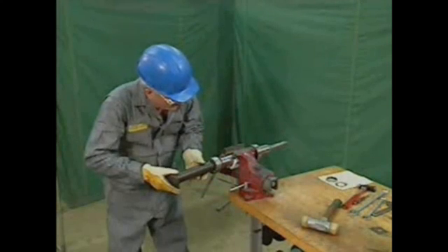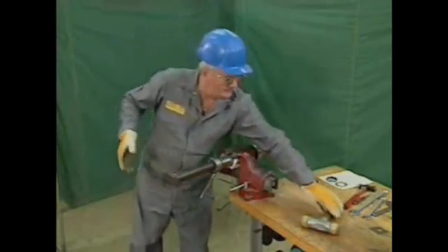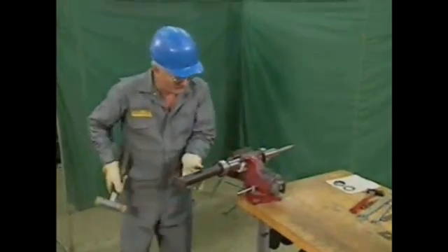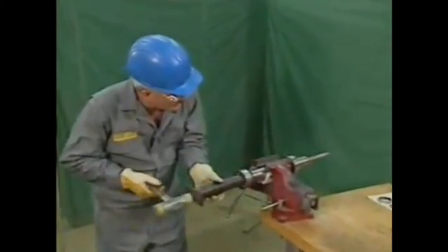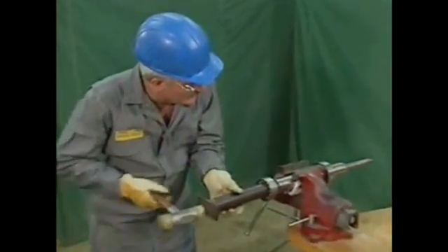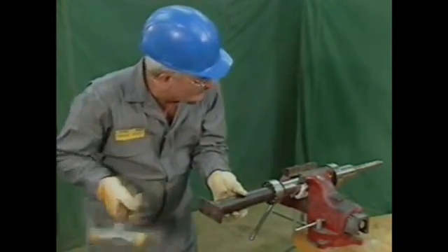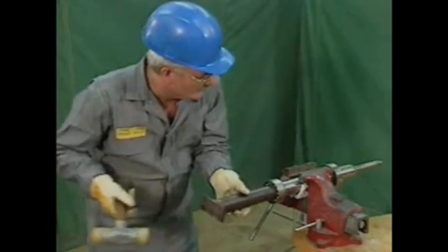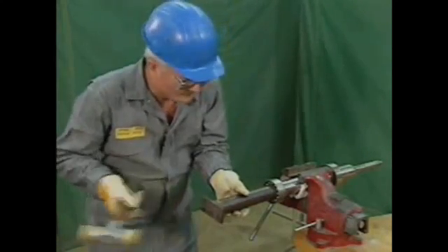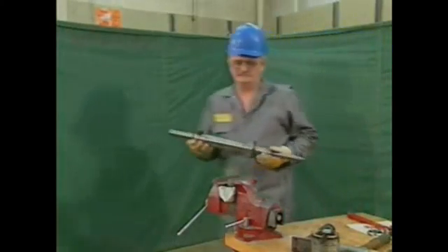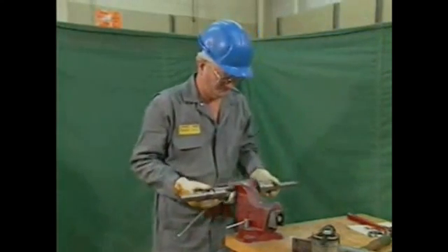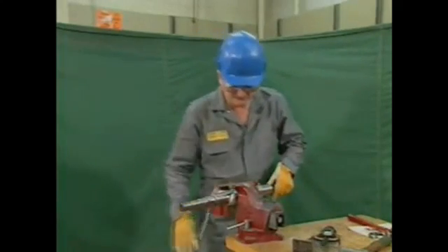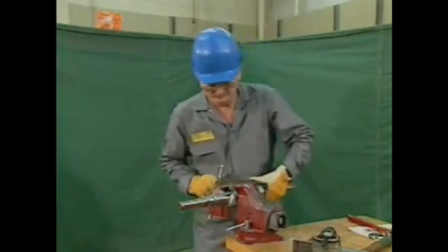When a tubular drift is used, the shaft stays stationary and the bearing is forced down the shaft. This method is generally used when the shaft can be removed from the machine and placed in a vise. If the shaft is left in the machine, its other bearings may become brinelled. The tubular drift method is both simple and efficient. Let's watch a mechanic install a bearing using a tubular drift.